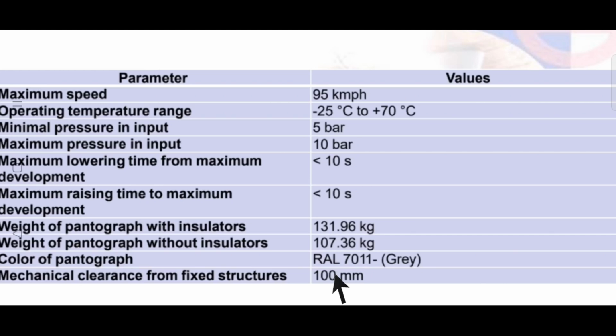In the pantograph strip, it has often been observed that a groove forms over the carbon strip, and the main cause of the groove was improper stagger calculation. So whenever we are analyzing the groove and its causes, we consider all these technical parameters, like how much the mechanical clearance is, and the length of the pan head, which we discussed, was around 1240 mm, and half of the length was 620 mm. So these technical parameters are also important for analysis in case of uneven scenarios, or in case of maintenance.